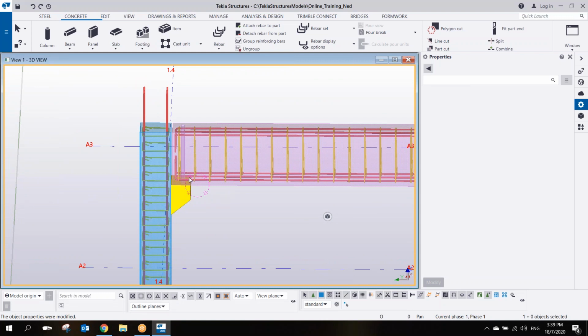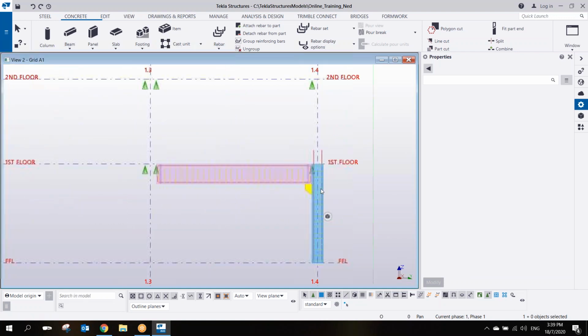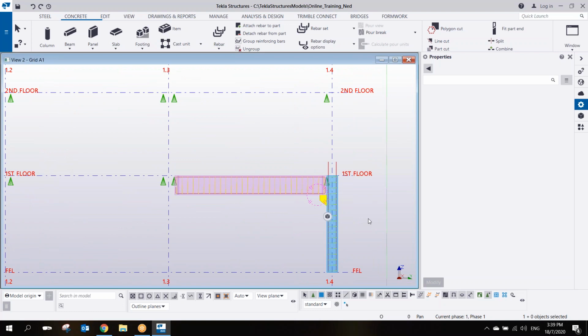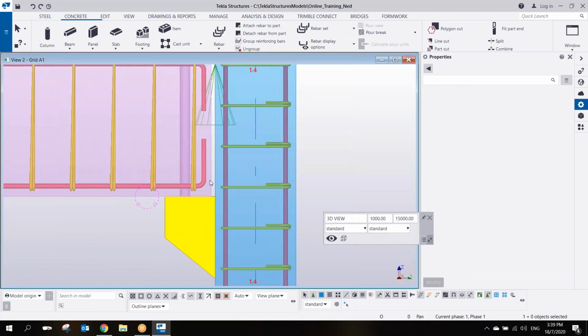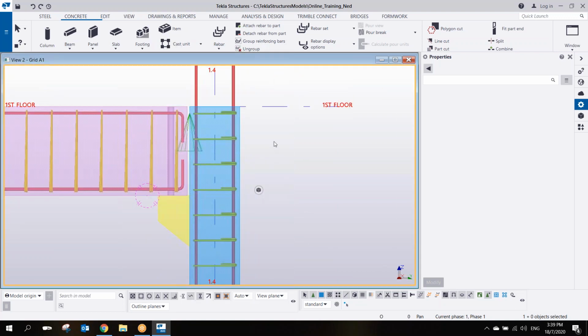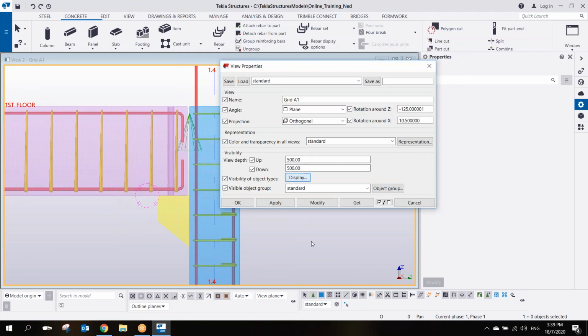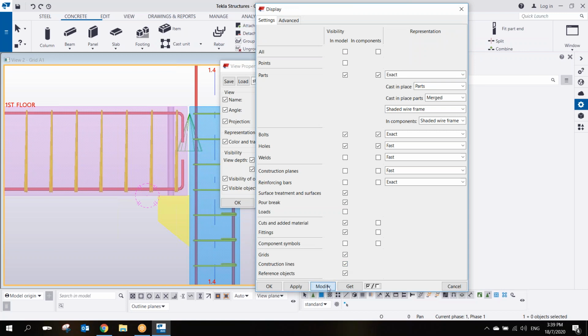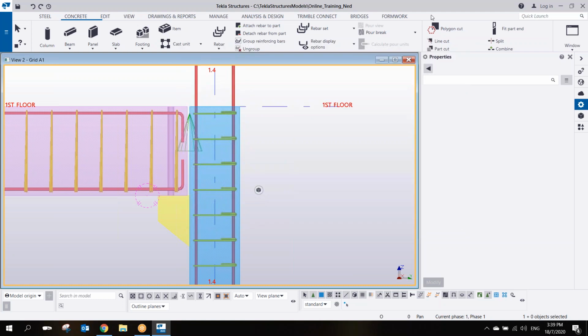So the issue now here is the corbel, and you can see that there is a dowel, and then the corbel. Okay, so first, let me add the dowel. All right, first, let me add the dowel. Let's add the dowel. So for the dowel, did I use a construction line here? Nope. The construction line, I need to add the construction line now.